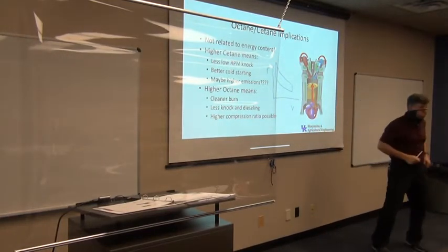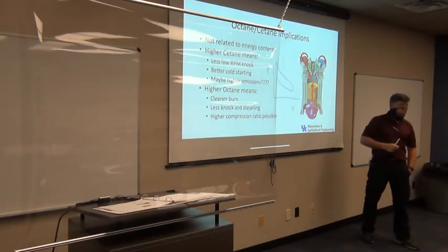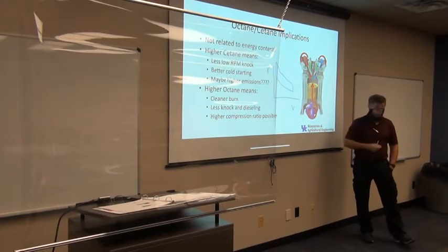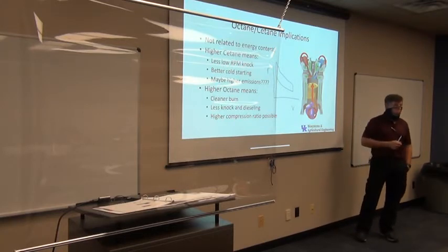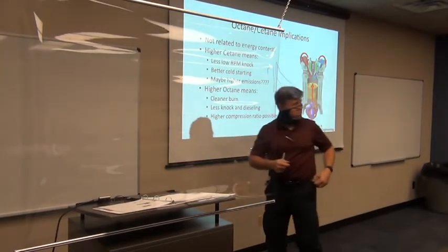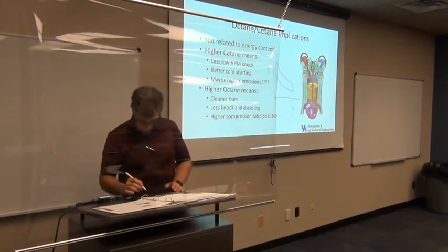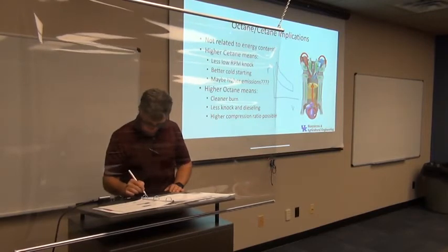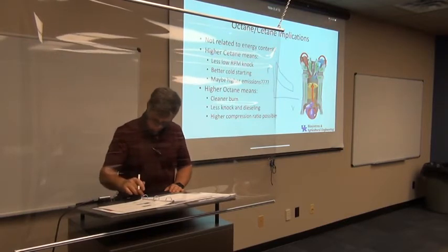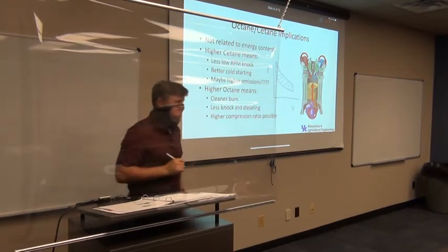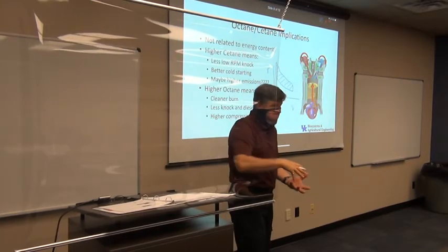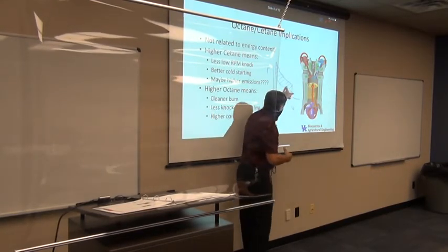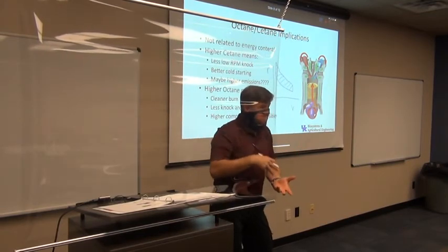How do I measure the power from that curve? The energy that I've gotten out of that fuel in that stroke, how do I measure it from that curve? Somebody said it. It's the area. Sure, it's the area between those curves. So this area between the curves is how much energy I have recovered from the fuel. That's how much energy has gone into pushing that piston down. And if I add the time and figure out how many times this happens, how fast that's happening, then I can come up with the power.